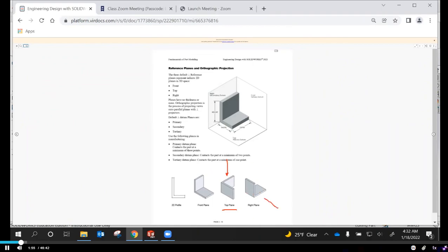So you're looking at it from this view, and it's the same sketch drawn on all of these, but when you show them in isometric, because of the selection of the plane that you chose to draw on, you end up with a different part, same part, just different orientation. So I want to stress the importance of proper orientation of your parts.